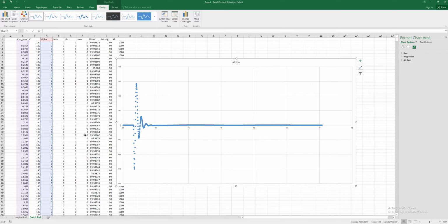So this shows that lateral modes are a full 6 degree of freedom response of the aircraft. You can't just look at lateral modes all by themselves. You're always going to excite the longitudinal modes, whereas with the longitudinal modes, we could excite them without exciting any of the lateral modes. That's just one of the things you deal with when looking at the lateral modes that you don't have to deal with when you're specifically looking at the longitudinal.